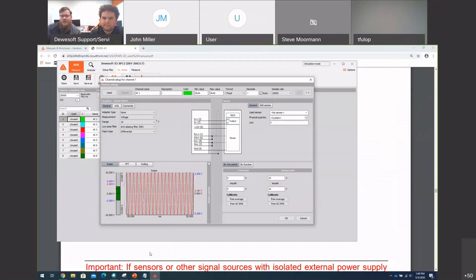Yeah, generally standalone units are going to have an individual ground port because you don't really know how they're configured, if they're isolated, if they're kind of just floating on a rubber mat or something like that. Whereas on a rack mount, generally speaking, that rack is grounded. So for the iLight rack, there's not a dedicated ground plug, if you will. Whereas on the modular units, there are, just because we're assuming that that rack is grounded as it should be, but there's no reason that you could not ground directly to the chassis of that iLight.